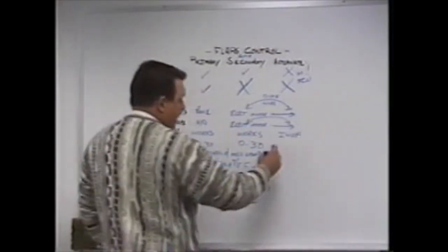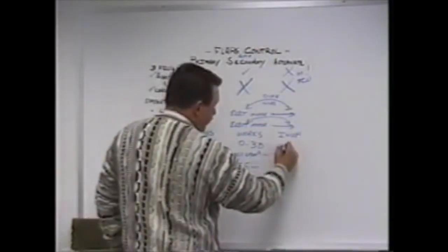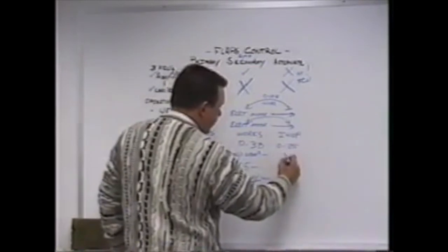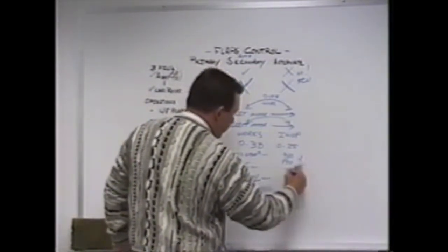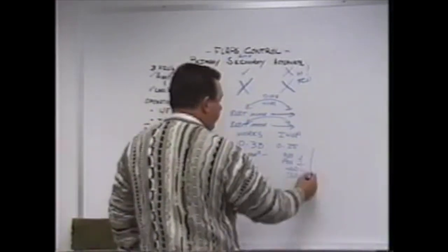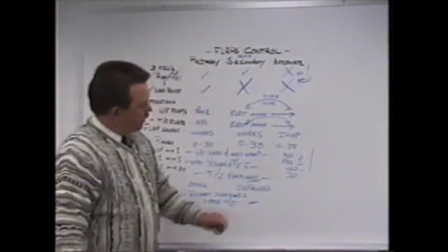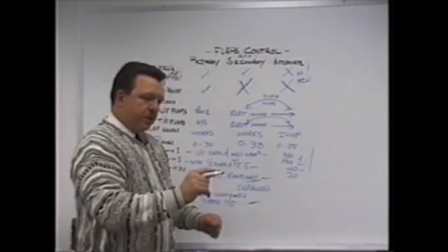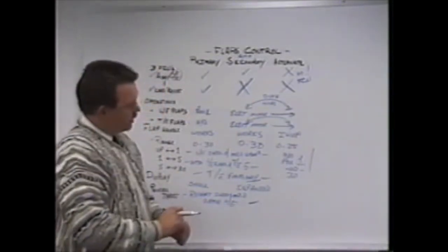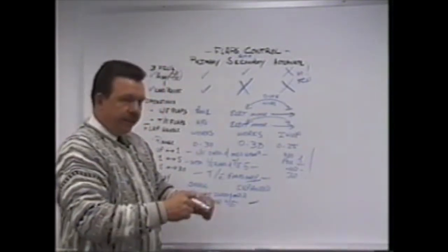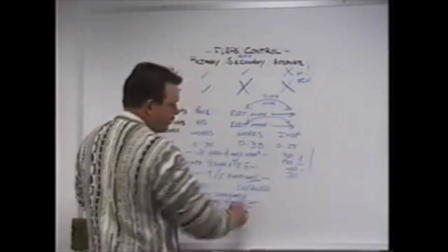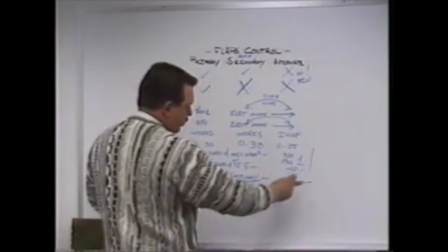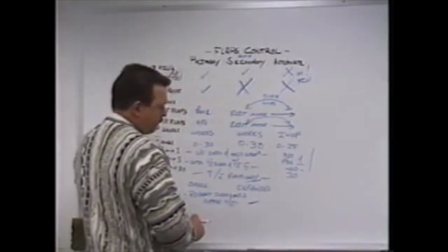What range can you select on the alternate mode? You can go from 0 to 25. There is no position 1 or 30 on alternate trailing edge flaps. Because when you take the arming switch to arm and then take your switch to extend, all the leaders and all the trailers come out at the same time. So there's nowhere to get partial leaders. Also, the flaps will automatically stop at 25, so there's no way to get to flaps 30.